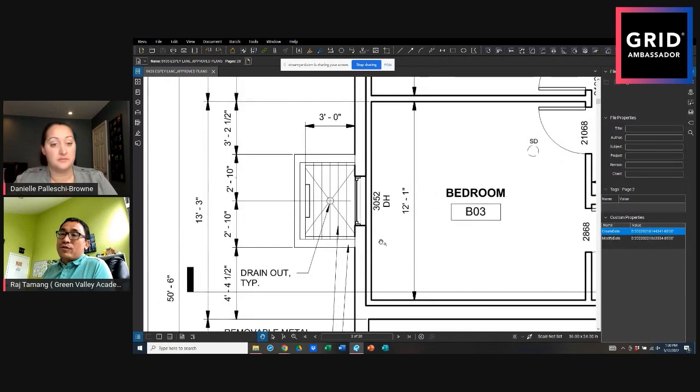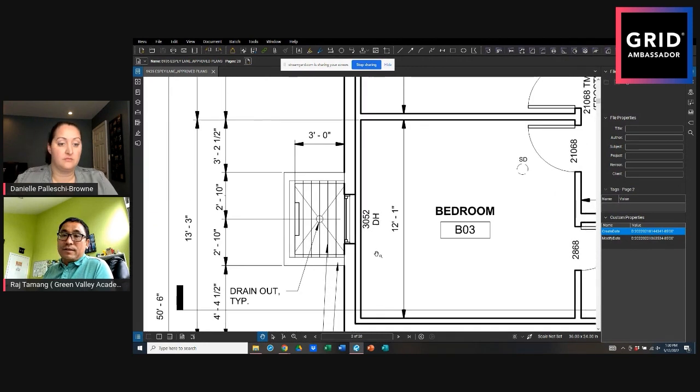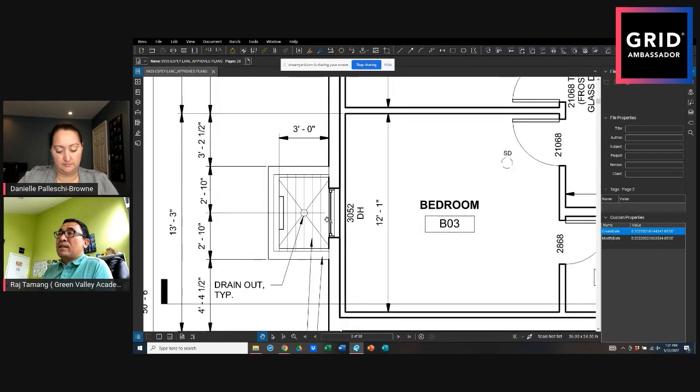When you have it, make sure that you have all the dimensions and the openings that meet the code requirements. So once you come out, let's say I have a window here, then you have to come out. Then you have to have a window well large enough so you can get out, right? The minimum is 3 foot by 3 foot. And when you come out, usually you have a ladder here. From the ladder, you come out. Yep. Okay.